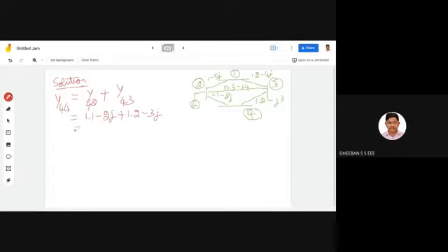So the Y44 value is 2.3 minus 5j. Okay, so you can just write the diagonal elements like this. The off-diagonal elements, or the transfer admittances, are very simple. You have to just negate the value, make it minus. Okay, so hence your Y bus will be equal to.